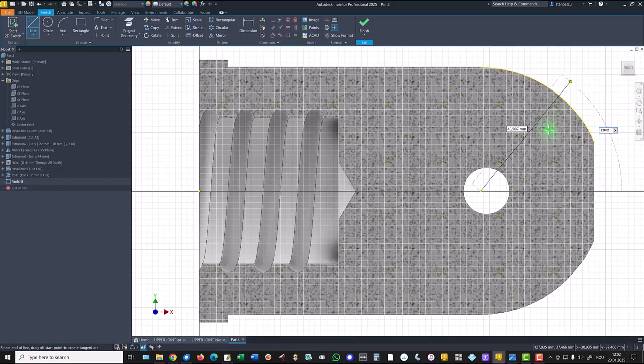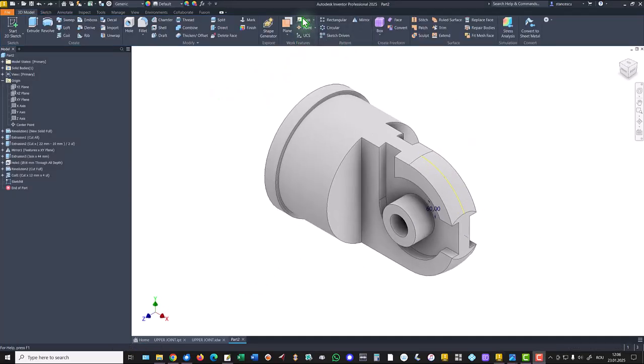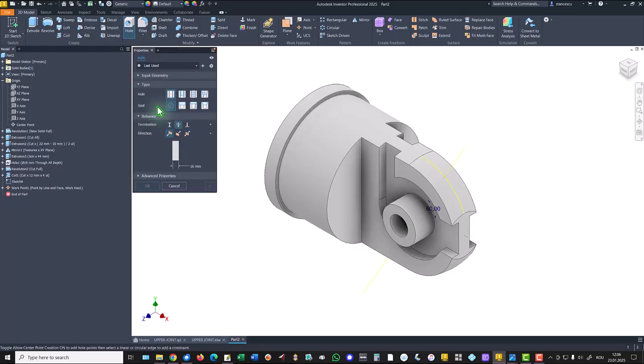and tap the circle. Yes, fully constrained sketch. Finish sketch. We create an axis based on this sketch, and selecting this line you see the new axis, then a point on this axis and this arc. The point is here. We can use it to apply a hole.